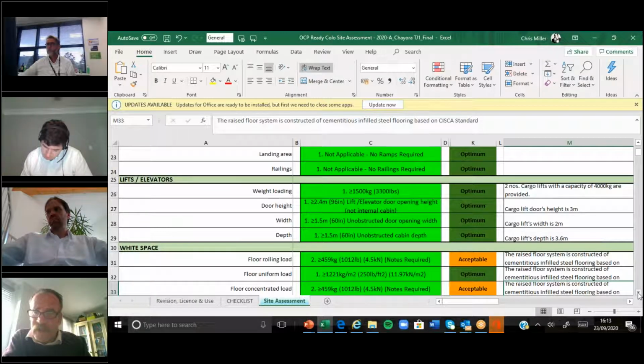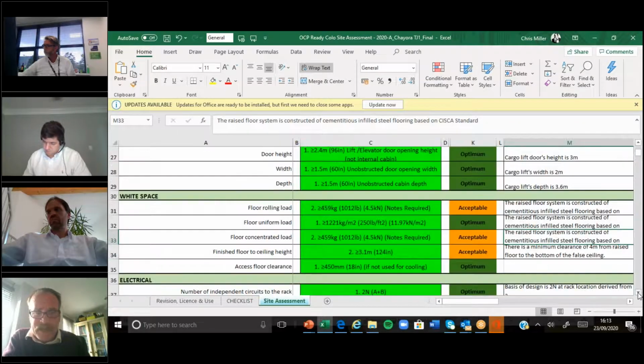However, we will come on to that later. The facility's been designed to a PUE of 1.19, and the data halls that we've been building are in 4 suites that can be controlled from a PUE perspective. And from the CFD modeling that we're doing and have done, we're very confident that we can go from 1.8 to 1.4 to 1.2 very rapidly in each of those suites. Any questions so far?